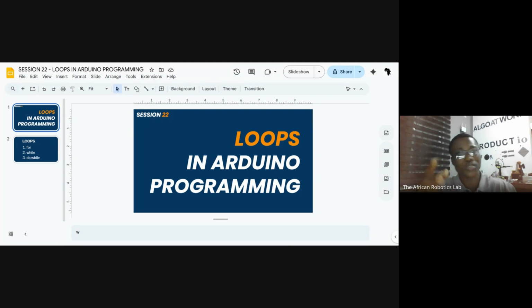Because in your system, sometimes you may have certain sensors that do not give you whole numbers, like 20, like 1, like 2. Sometimes some sensors are going to give you something like 20.4, 20.1, 21.2, 4.5, 3.7, like a voltage. We represent voltage in terms of decimals, right? So you have 4.2. Even if the voltage is 3 volts or 4 volts, you have to say 3.0 volts, 4.0 volts, 3.7 volts. So to record or store that type of data, I use the float data type.